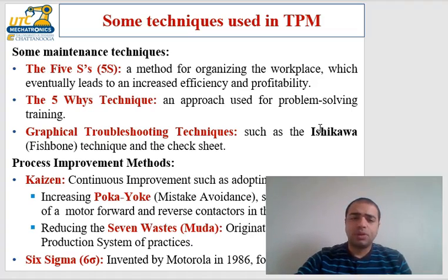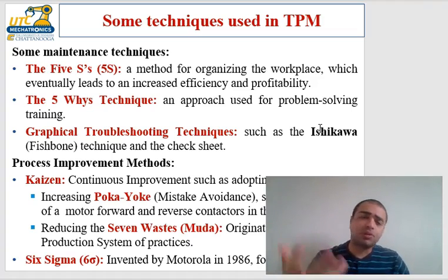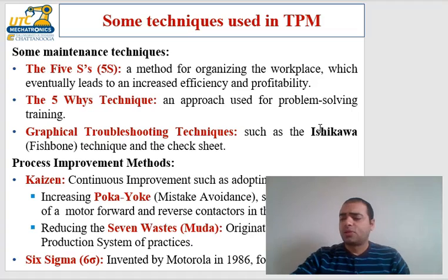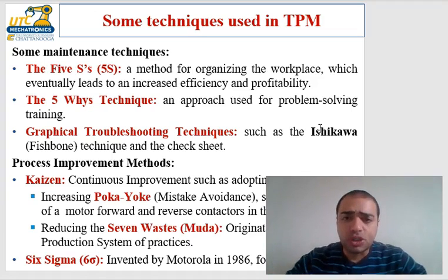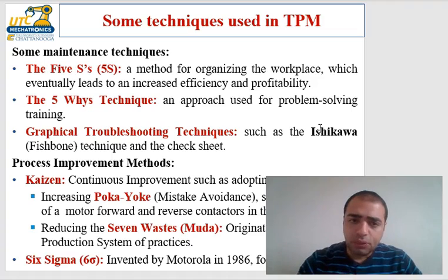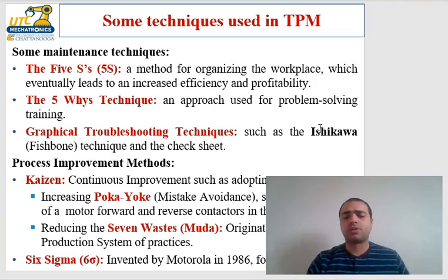For instance, if you have a process in which there's a sequence of events that have to take place. Like, for example, you have to mix 2 chemicals, but first you have to get water, put water in the reaction tank, and then after that you put, for example, the base or the acid. Typically, this is the situation. So in other words, there's a sequence. So you design the equipment such that if the operator tries to, for example, insert a base before the water, they cannot. So they are forced to follow the sequence. So this is called poka-yoke.